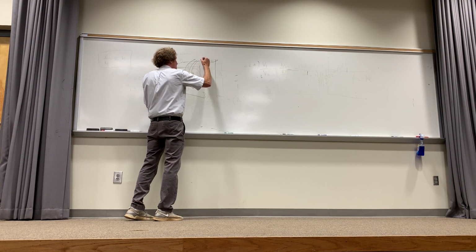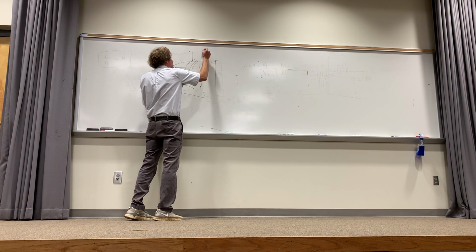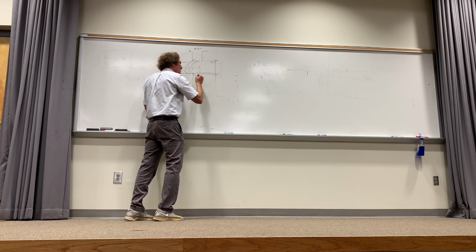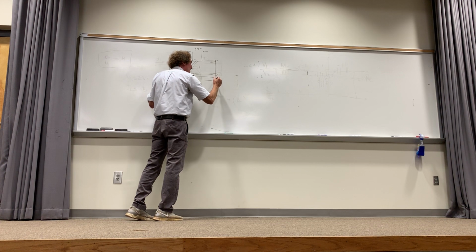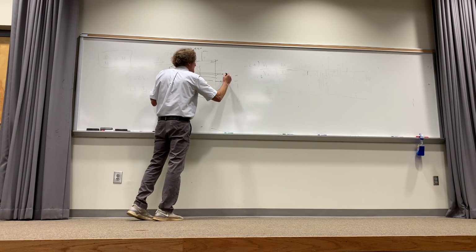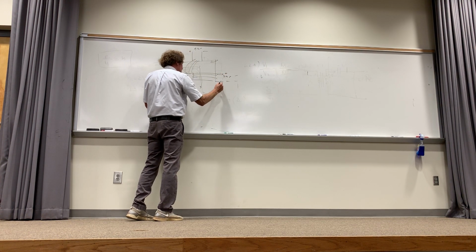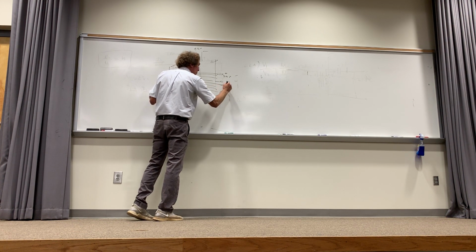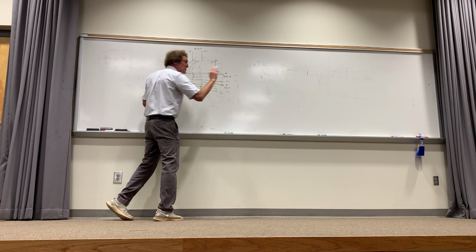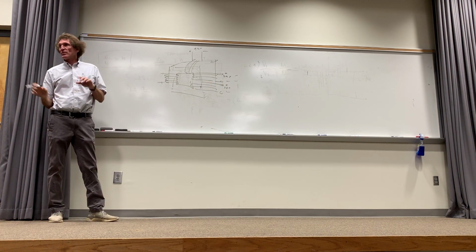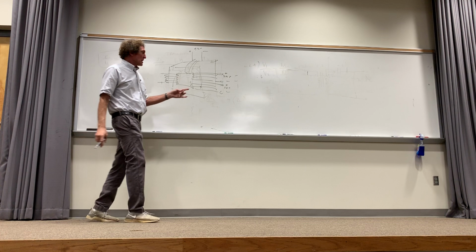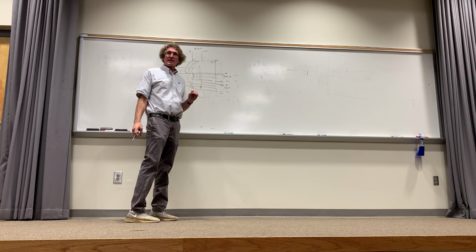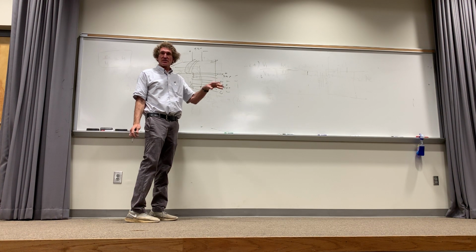And that's not showing the perspective, but now this is going to be plus or minus 480. Then I'll have another set here, fewer turns yet, coming off, and I'll have plus or minus 240, and then another set here, plus or minus 120, or as many voltages. That's common. Then what's typically done a lot of times, we're not there yet, is they put it through something called a rectifier that'll take that AC signal and turn it into DC.